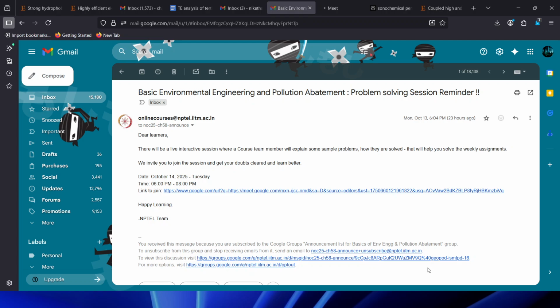What about the last one, the wet scrubber? Ma'am, water is added from the top and gases from the bottom. How is water added? Can we just pour water? I mean, water is sprayed, like into a jet form. Jet.